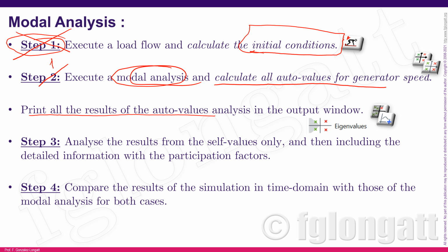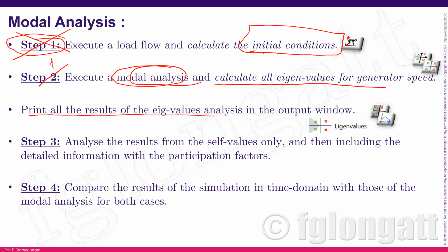Or also, if you want, you can create a plot, okay? There is a very specific plot to show the eigenvalues. If you go inside PowerFactory, there is a very specific plot that we can use to plot the eigenvalues. I will show you that in a minute, okay? What is important is that PowerFactory allows you to have a look and identify the location of the different eigenvalues using a graphical representation, okay?